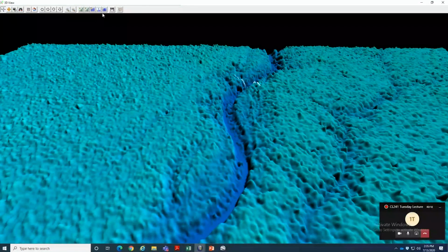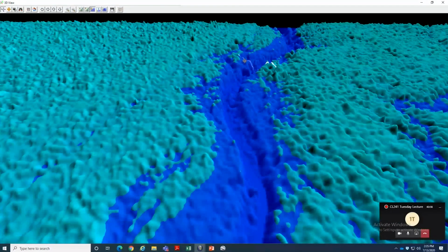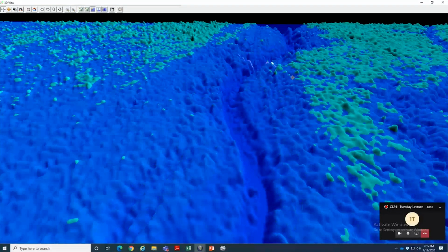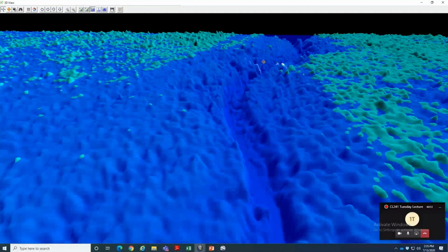Now let us see, I'm going to fill the water. Okay, now water is flowing in the river, almost bank full, almost filling the river. Now if I increase the water one more, you can see this area where the construction is, that area is already under water, whereas the opposite bank is not going into the water. Now if I increase one more, this part is still not underwater, but almost the first floor of the building will be underwater. So with a little more calculation, I can understand which part of this area will go underwater.